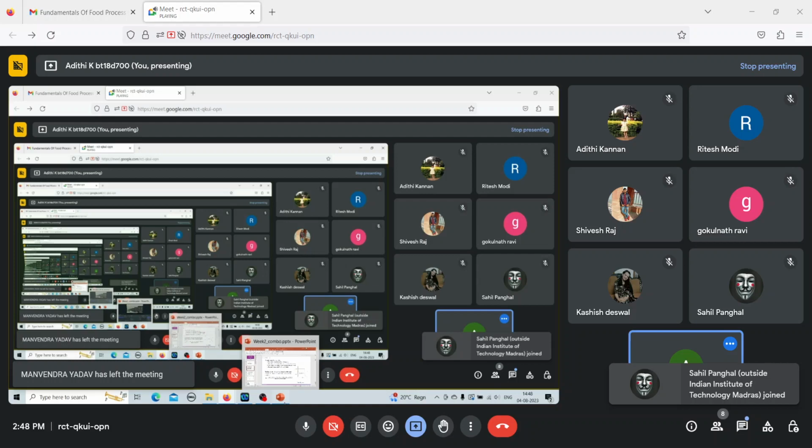Had it been an elastic material, you would have to apply the same stress throughout, and your stress versus time graph and strain versus time graph would look exactly the same. Because it's a viscoelastic fluid, the amount of stress that you need to maintain the strain drastically reduces with time. Is this part clear? Is this getting confusing? If you want me to repeat in a simpler way, please let me know.